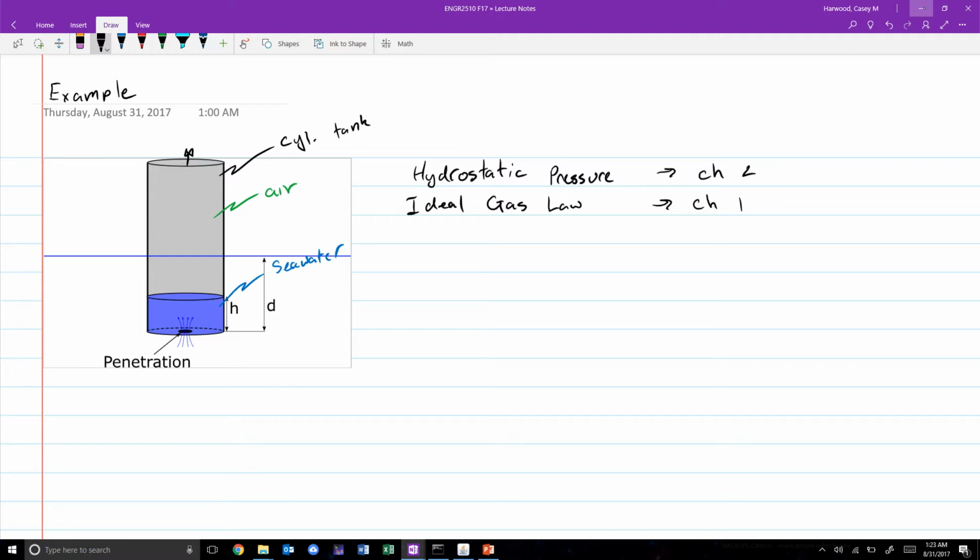All right. Then when it chooses to reascend, or if it wants to remain neutrally buoyant, there will be some source of air, a tank of compressed air or something, which will be used to blow air into the top of the tank, increasing its pressure and driving some of the seawater out through a penetration in the bottom.